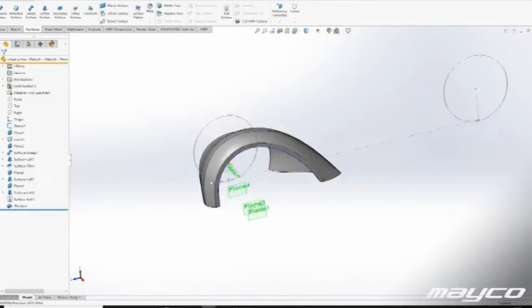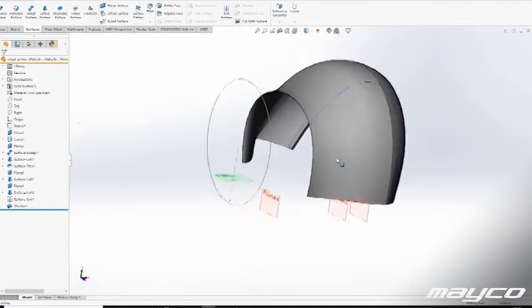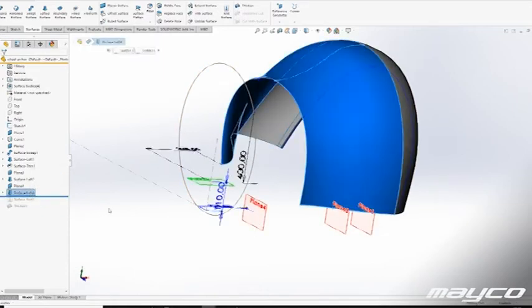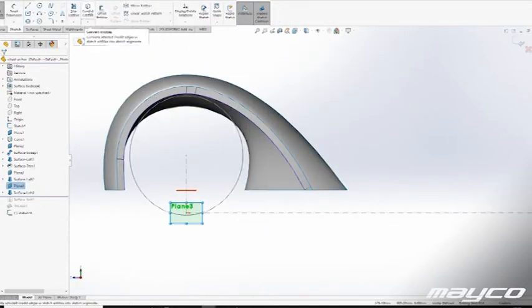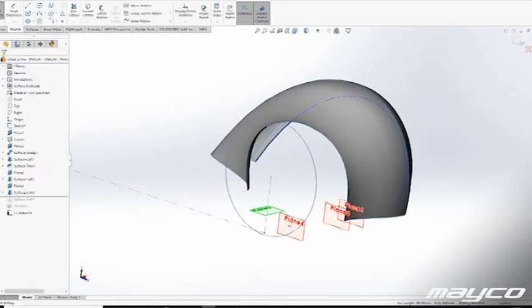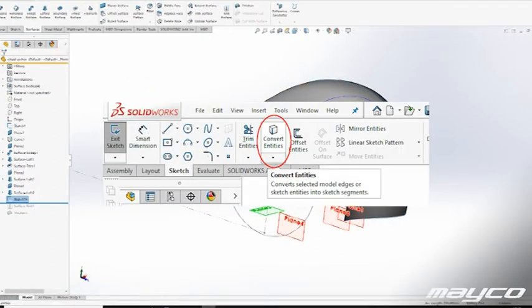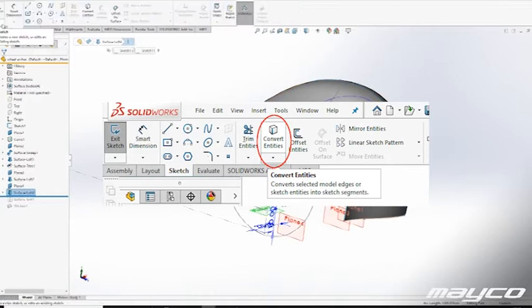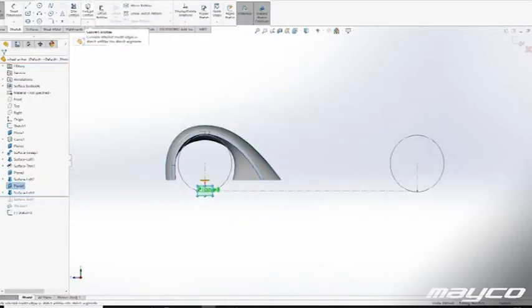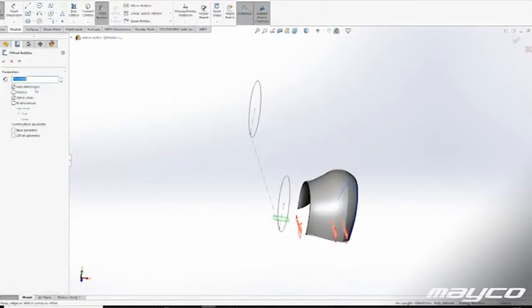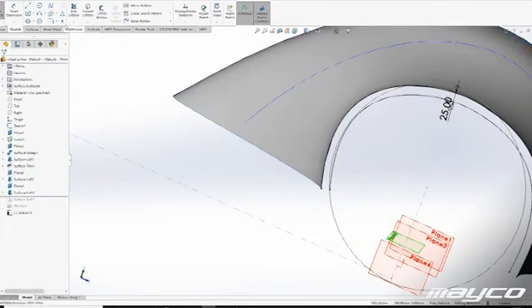And when it doesn't, that's quite annoying. So what you then do is you make a new sketch and you say copy these lines and make it into a single sketch. And when that sketch is done, you close it off and you can use it. You'll see me do that several times.